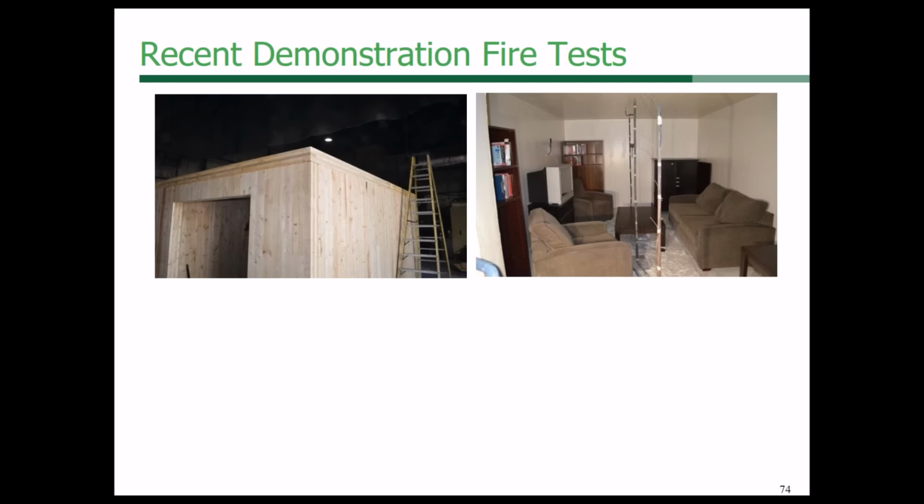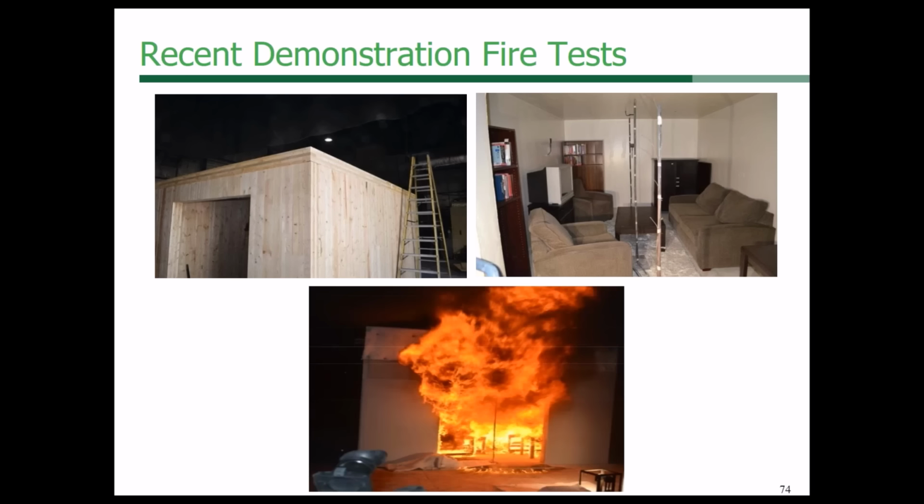There were about 5 laminations thick. The 2 tests, one had a nail laminated timber ceiling, and the second one had a cross-laminated timber ceiling, and had a load of 40 pounds per square foot. And they all were covered with 2 layers of 5/8 Type X,